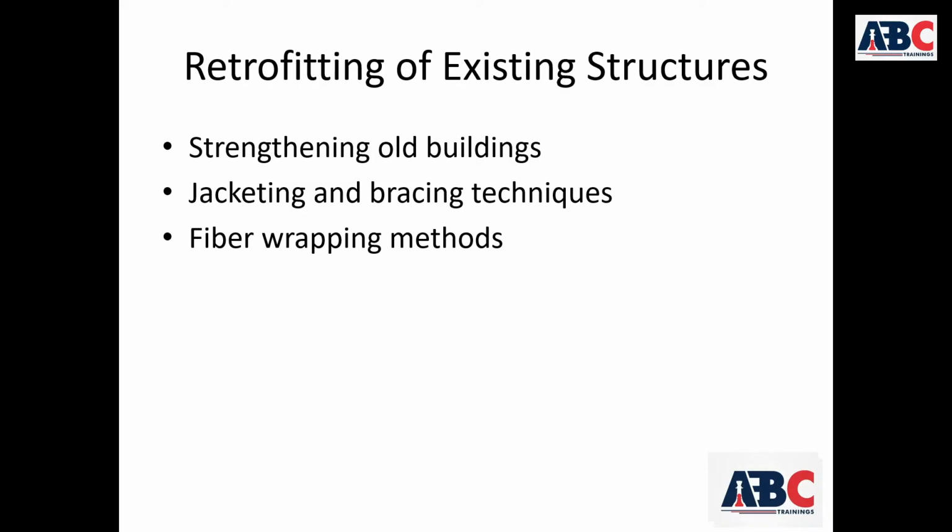The third point is fiber wrapping methods (FRP). Wrapping is a modern retrofitting method. In these techniques, fiber sheets are wrapped around columns and beams, and epoxy resin bonds them to the concrete.